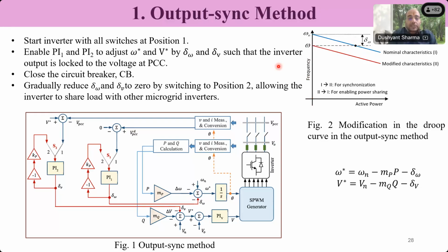So how do we do this? We modify the control a little bit. We use the additional signal which is named delta omega. If you see here, what this delta omega is doing is trying to match the voltages in the d axis, and similarly in the q axis this voltage will be matched. One of them has to be 0, as we discussed. Any one can be made 0. So we compare with 0. We pass it through a PI controller, and the PI controller will make it delta omega.